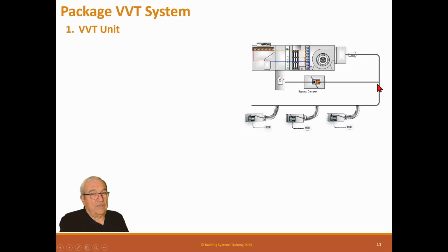What it does is if we're using air and we've got enough air, we don't need anybody to start shutting down. More air is going through here, so now all of a sudden this unit sees, whoa, it got cold fast, it can shut off the compressor. So it's basically capable of doing that.